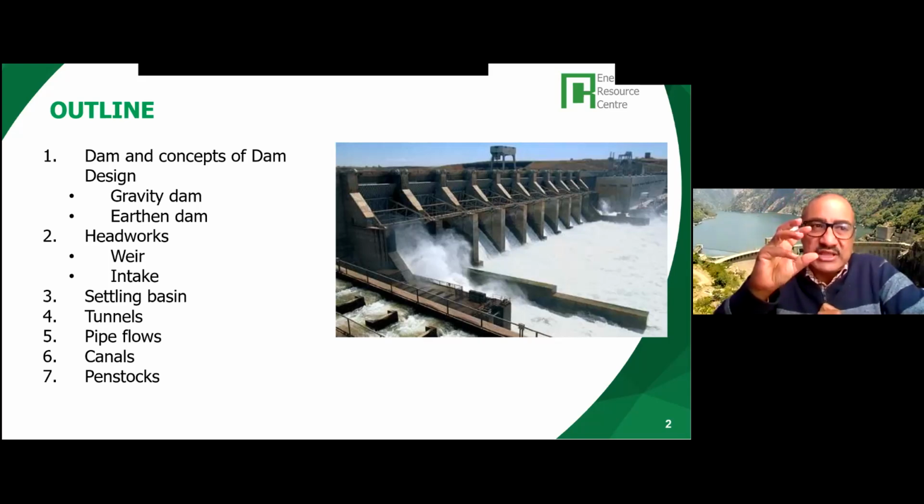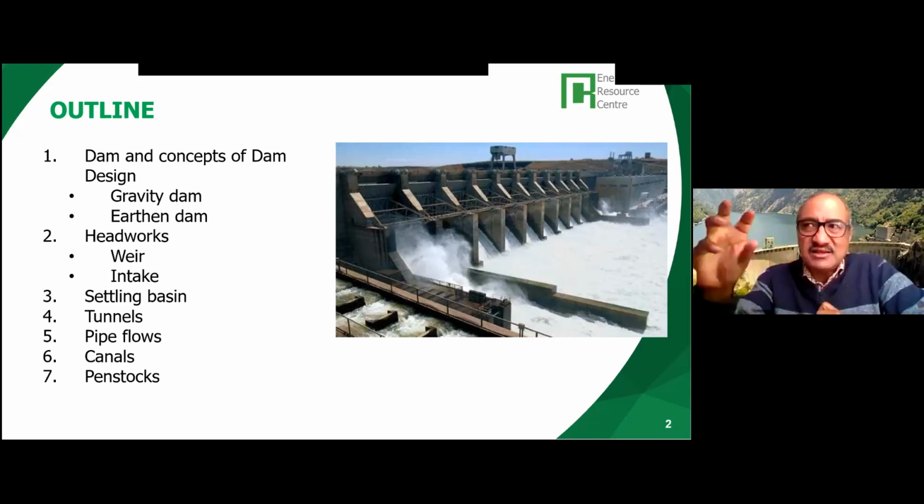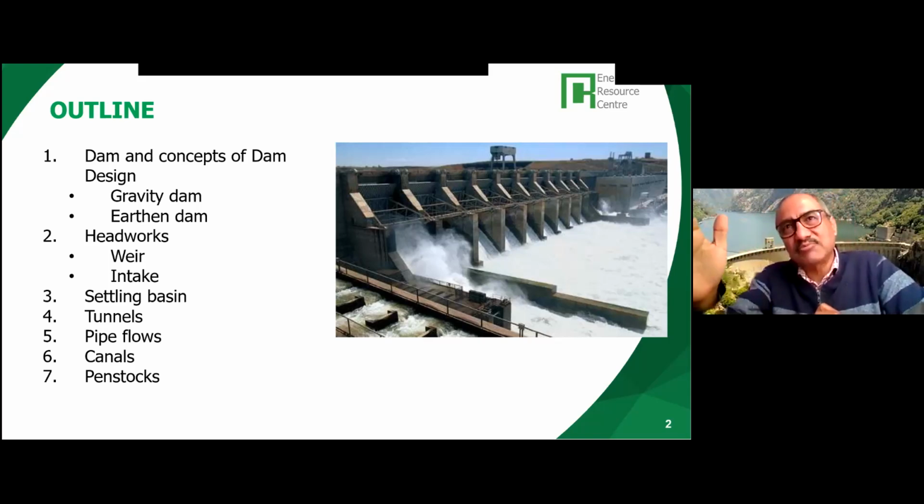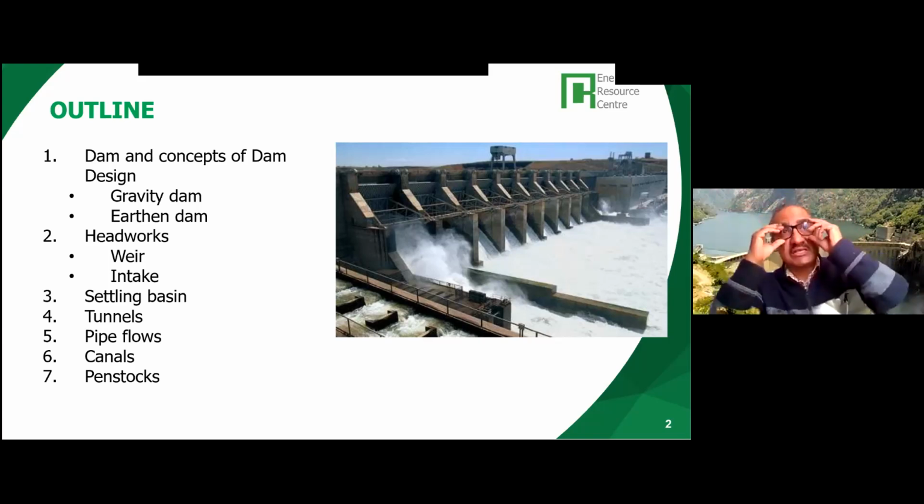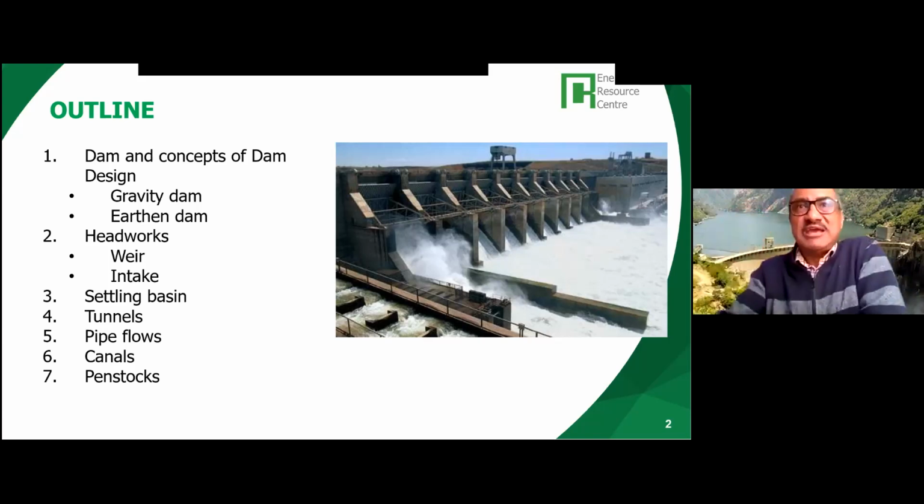But today, just to give you an idea of how these different civil works are: as you know, there is civil works, electromechanical, and hydromechanical work. Civil works, depending on the project, can be 40, 50%, or up to 60, 70%. For large hydros, the civil works component can be high. For mini hydros, it is maybe about 45, 50, 60% of the cost.